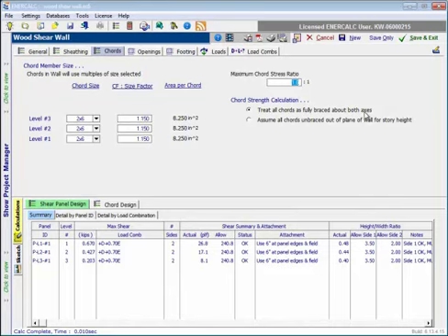Now, I'll say that this is probably not the typical option that would be selected. Let's think in terms of a physical analogy here. One way that this could potentially be a viable option to select is if you happen to have, say, a U-shaped or a T or an L-shaped framing configuration of shear walls such that your chords were always intersected by walls at, say, 90 degrees to the wall of interest, such that the sheathing within the plane of the shear wall being designed obviously prevents buckling in one direction, and we'll envision that a shear wall would prevent buckling in the out of plane direction of the wall being designed.